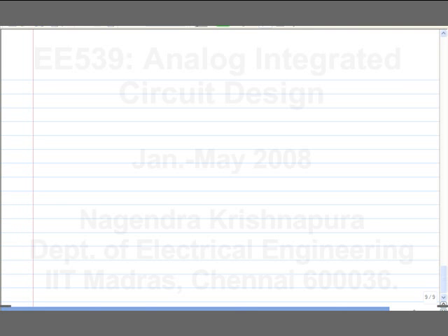For instance, if you determine the poles using the method of open circuit time constants, you then evaluate the DC gain from your particular input to the particular output you are interested in, and divide it by 1 plus s/p, where p is the effective pole that you calculate. So where you apply the input and where you take the output only change the zeros, not the poles.